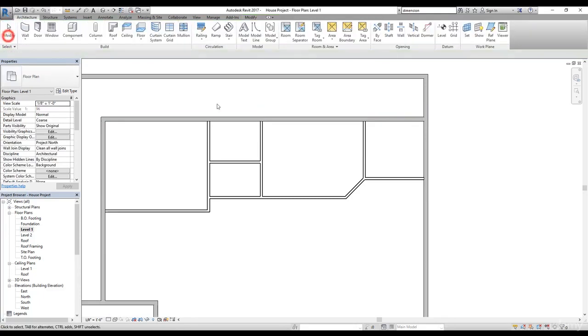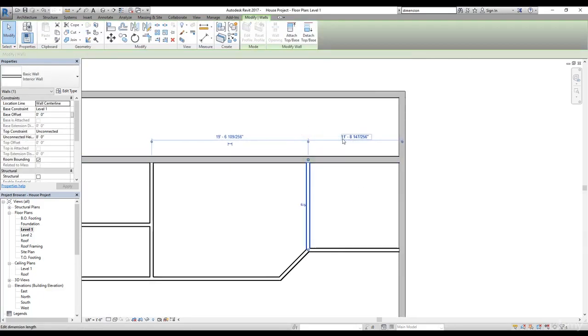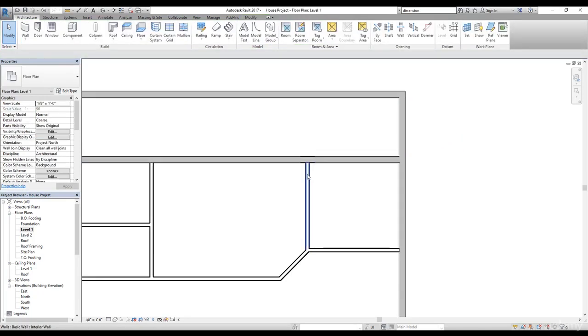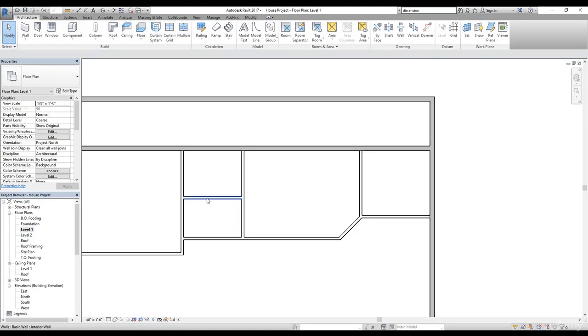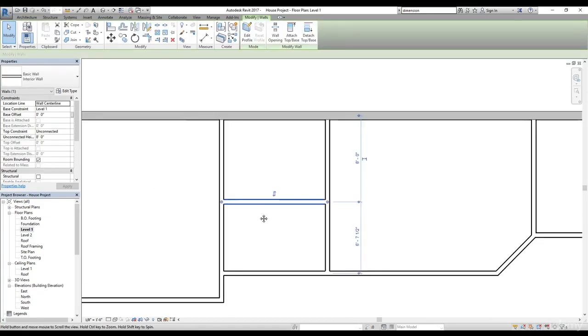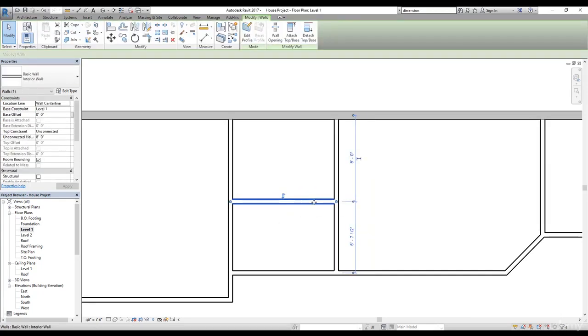Now I'm going to select the modify tool, and let's check out the dimension for this. So this is about 11 feet and something like that. I'm going to click on this pivot point, and now we can see we got 11 feet. So I'm going to change this to 12 feet, to make it more precise. Right. And then there's going to be two rooms. Let's fix this. Now we have this here, right? I want to make sure that I bring that into the center.